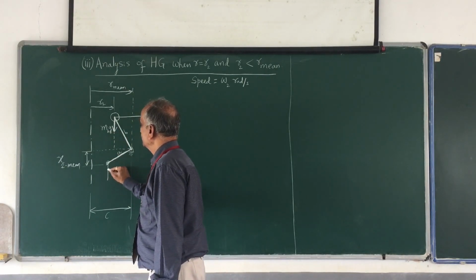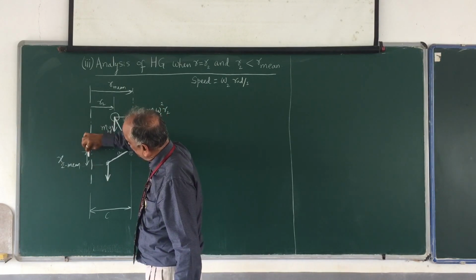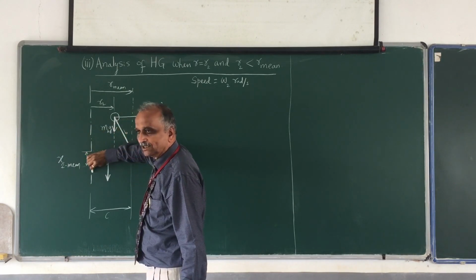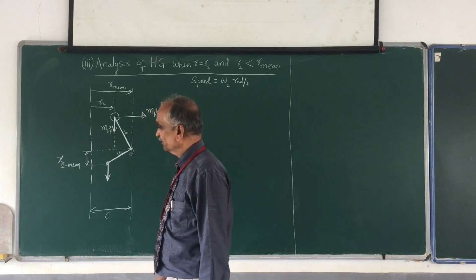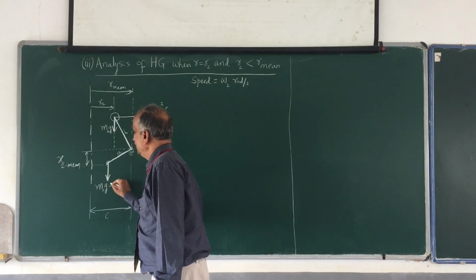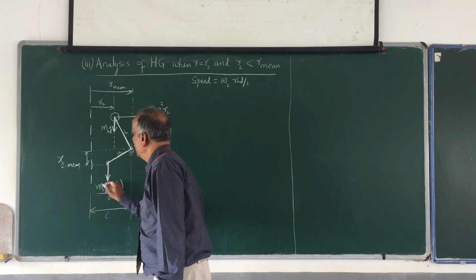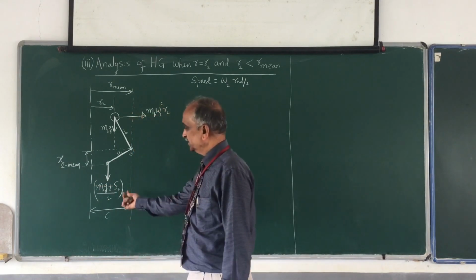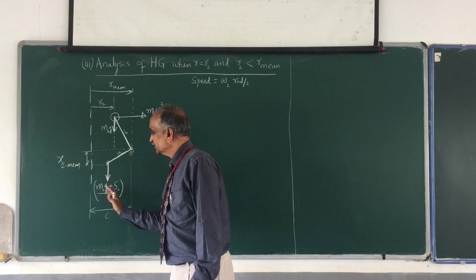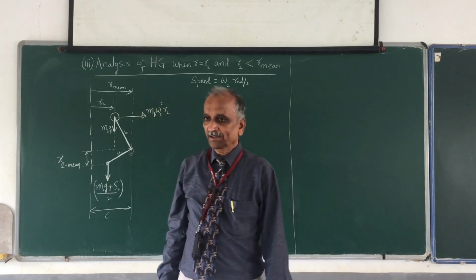At the roller, I have the central force. This is the sleeve here, the weight of the sleeve is acting in the downward direction, also the spring force. So I shall write it as (Ms into g plus S2) divided by 2, because I am taking only one half. Exactly the same amount of force you have on the other side also.